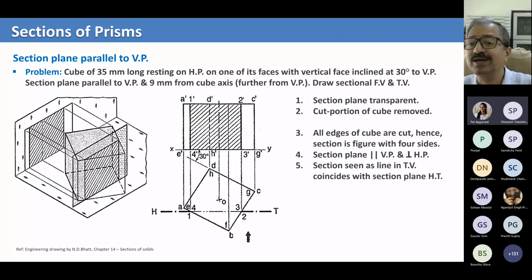Yeah, correct. Because now this sectional plane, although we have put a boundary here, otherwise we will not know where the plane is, right? Supposing I have not put this boundary on the sectional plane, how will you know there is a sectional plane there? Correct. So therefore we have to put something. HT, the H and T can be anywhere. Thank you for saying that. Okay, it's an infinite sectional plane. You can say that. But to represent that, so that we understand it, it is represented as a line. That's why I said it is outside the object, right? But outside doesn't mean that it is only limited by this. It can be an infinite plane, not going through the object. Okay, thank you.